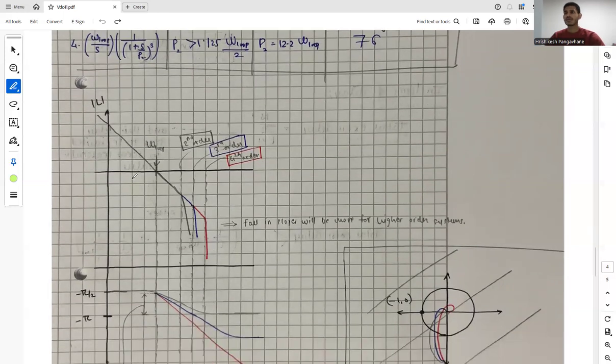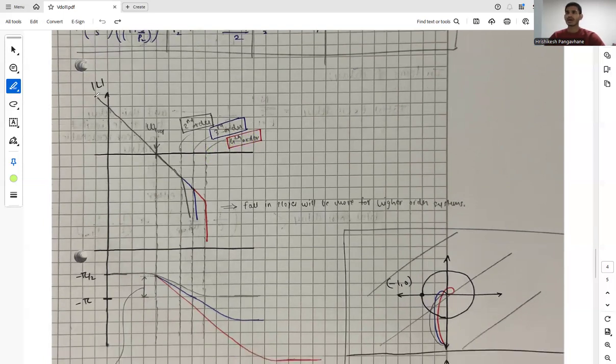So when we have one pole, or two identical poles at P3, which is a third order system, or three identical poles at P4, which is a fourth order system, a ramp will decrease properly and it will shift. So it will basically shift to an even higher slope when we have a higher number of poles. As we know, a pole introduces a shift in the decrease of its function by minus 20 dB per decade. So this is how our second order system will behave.